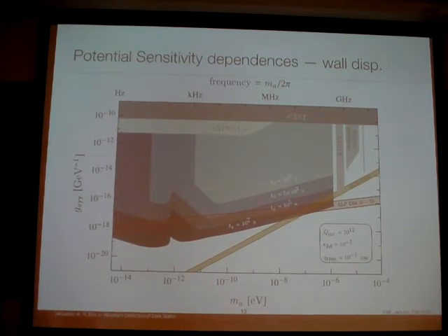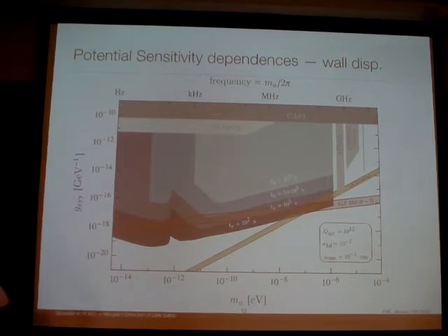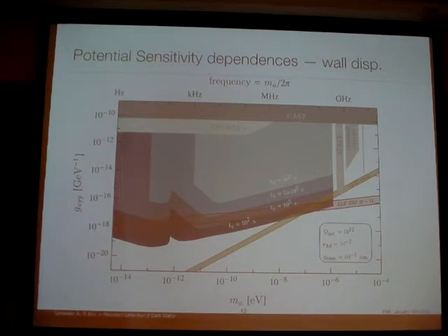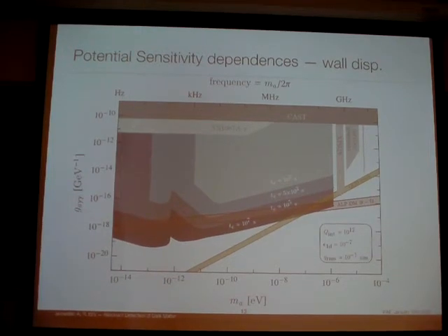And so you look up the phase noise, but then there's the impedance matching and the coupling and the resistive component of noise for the oscillation. Yeah. And then you mentioned briefly the amplifier. All those things kill the Q. Yeah, so the loaded quality factor of the cavity is like 10 to the 9 or so. Right. That's achievable in principle, but then you have to have a quantum limited preamp, which is no feat.